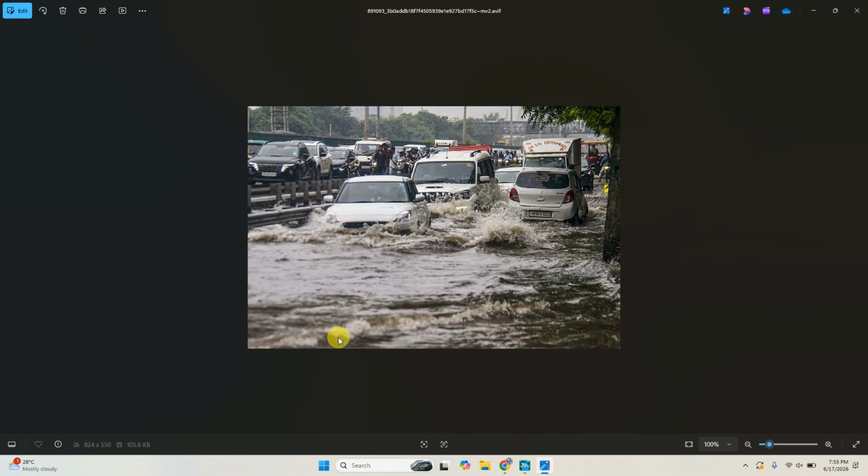But in urban areas, imperviousness is more. When runoff takes place or when precipitation takes place, if there is no stormwater drainage system, then too much inundation will take place in the societies, on the railway tracks, on the roadways. A stormwater drainage network is very important for an urban area.